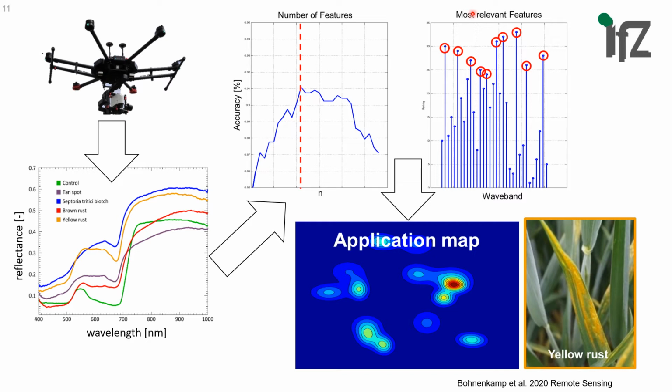This approach was followed in a field study where a hyperspectral camera was mounted on a UAV platform and in parallel on a ground-based vehicle. The spectral signatures were processed by a feature selection algorithm which provides the number of relevant features for disease detection and the 10 most relevant spectral wavelengths which were necessary for the detection of diseases within the field.